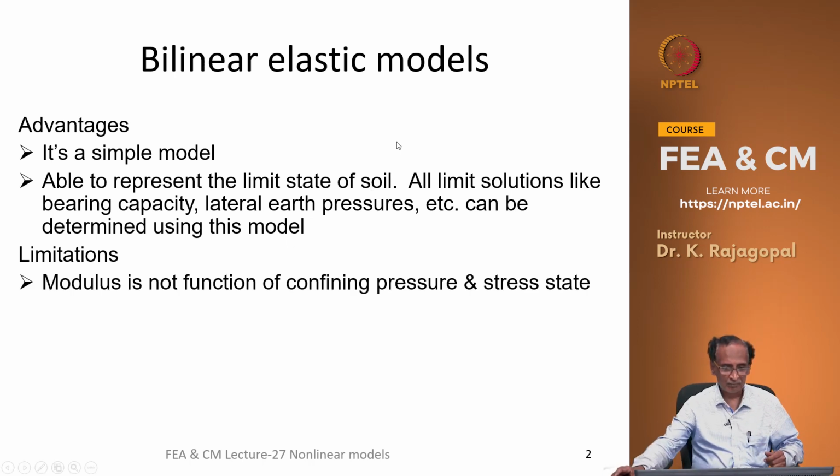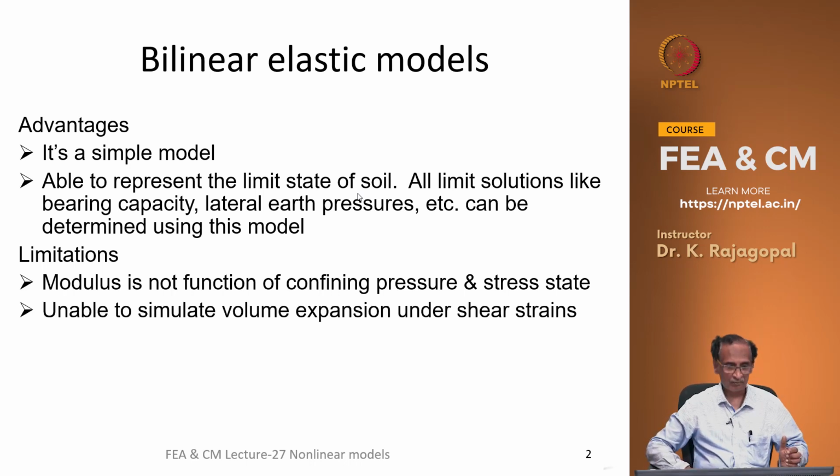The modulus is not a function of the confining pressure. See, this is one of the most important features of the soil. At a higher confining pressure, the soil will exhibit a stronger response in terms of the strength and also a stiffer response in terms of the modulus, and that we are not able to simulate by using the bilinear elastic model.